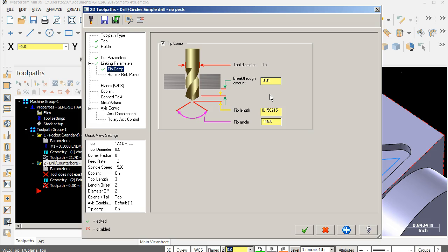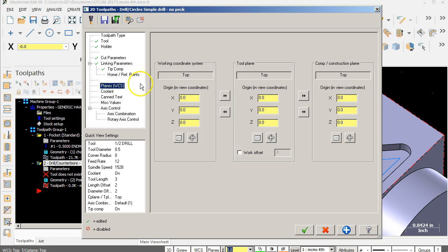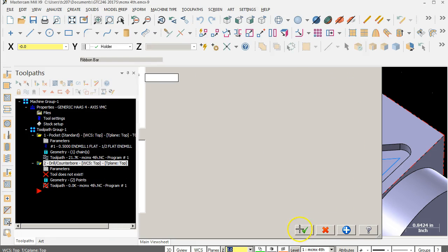This is where working above center line, you're getting that convenience on the setup, not having to set up all of those work offsets, but you're having to manage and see those values that in the 2.5 axis world and the 3 axis world, we're typically touching off on the top of the part and going negative. So here we're going to have some positive values to contend with. And then planes, we're still in the top, so we're okay.